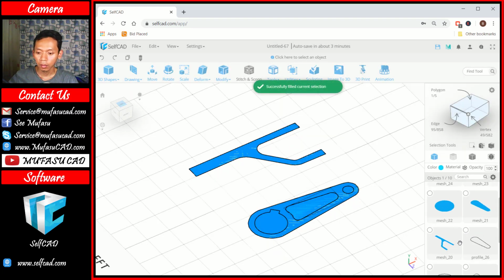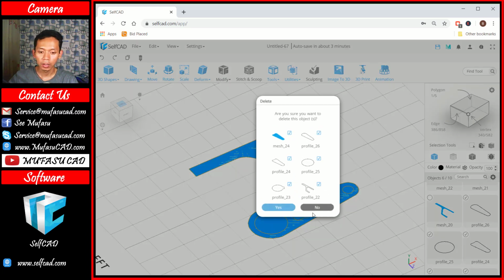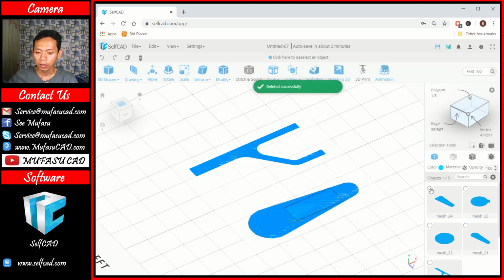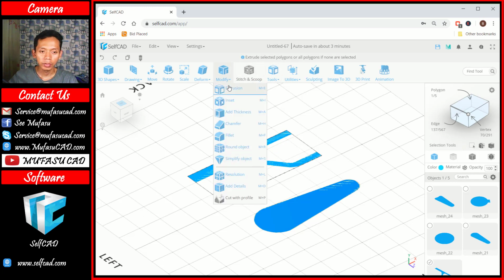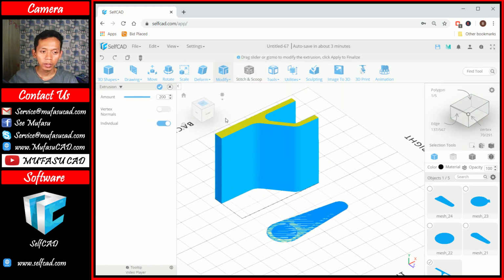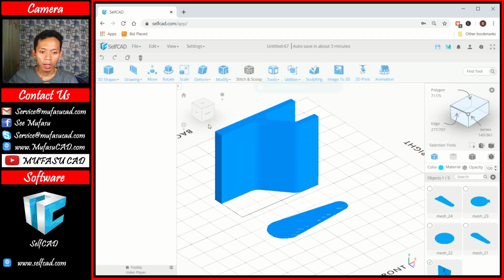Okay, now we already have 5 profile, and then I will delete this objects. Okay, you can delete, and then we can click yes. So to convert this mesh objects, we can use extrusion. I will click at this object, and then I will use extrusion. So we can extrude into 200 points. You also can uncheck this individual option, and then we can click OK to apply.